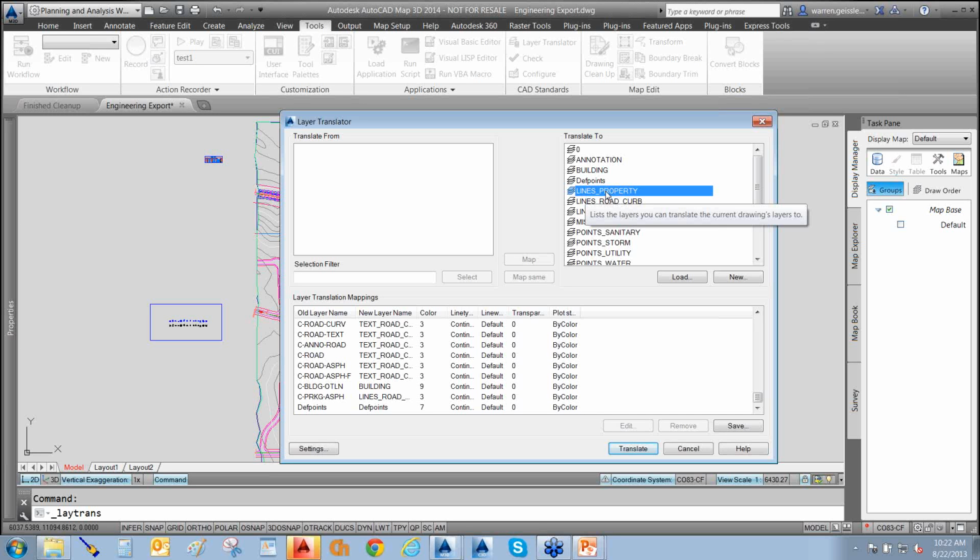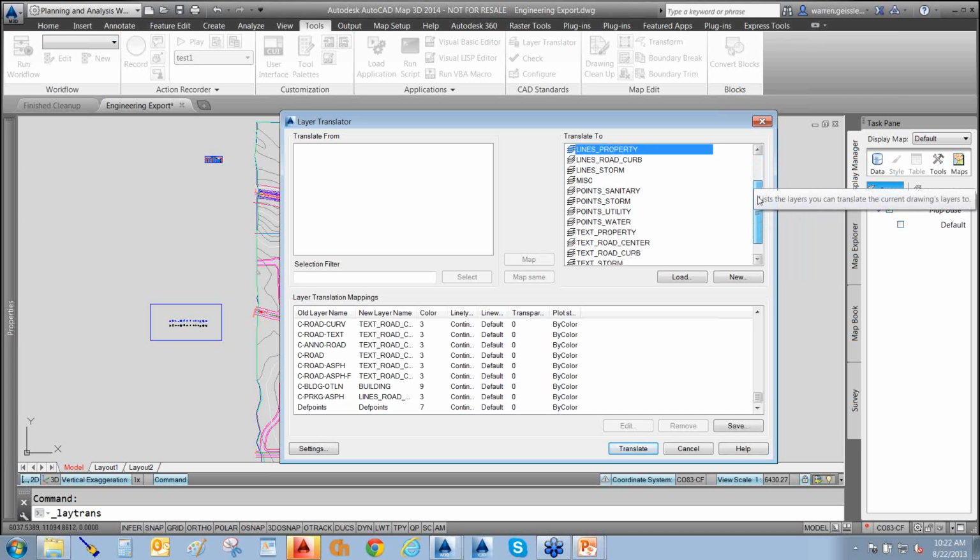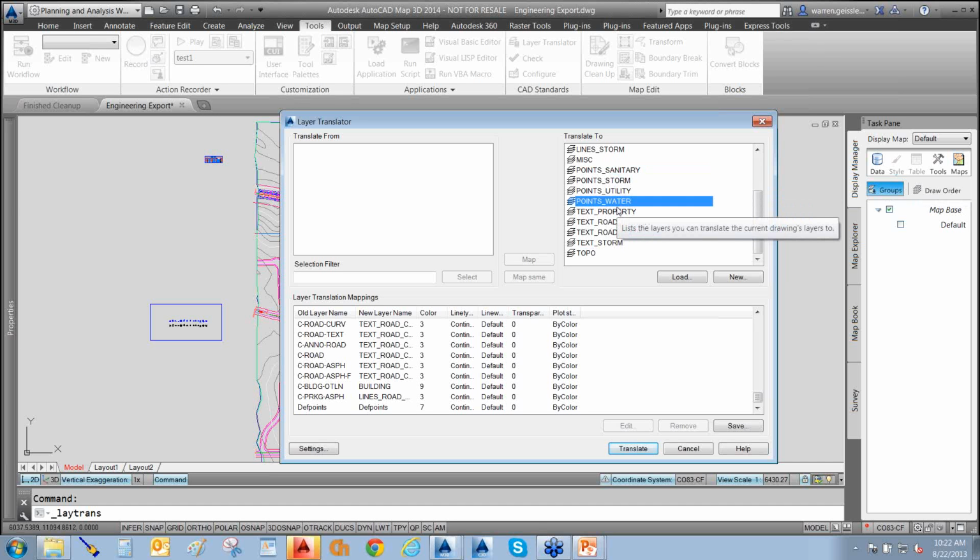When you're doing this, what I'm doing here on the right-hand side is I'm doing two things at once. You can define any, what we call a feature class, or in AutoCAD we call them layers. Here's storm, here's sanitary, here's water. You can do any number of layers, feature classes that you want. But what's most important is out of those layers, you have to split things down into 3 types. Not 1, not 15, 3 types. If you've only got 1, you can use it, but no more than 3.